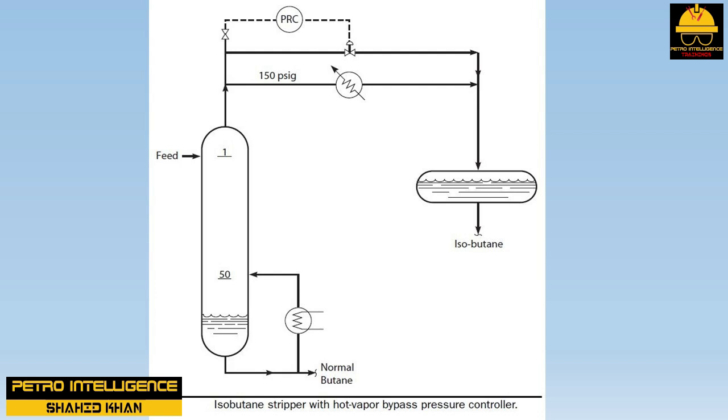As the liquid in the reflux drum is at its bubble point, reducing the reflux drum temperature will reduce the reflux drum pressure. As the stripper tower pressure floats on the reflux drum pressure, the pressure in the tower will also decline. The net effect of reducing the stripper pressure was to greatly reduce the amount of isobutane in the heavier normal butane bottoms product. There is no doubt most of the improvement in fractionation was due to enhanced tray efficiency, which resulted from suppressing tray deck leaking or dumping.